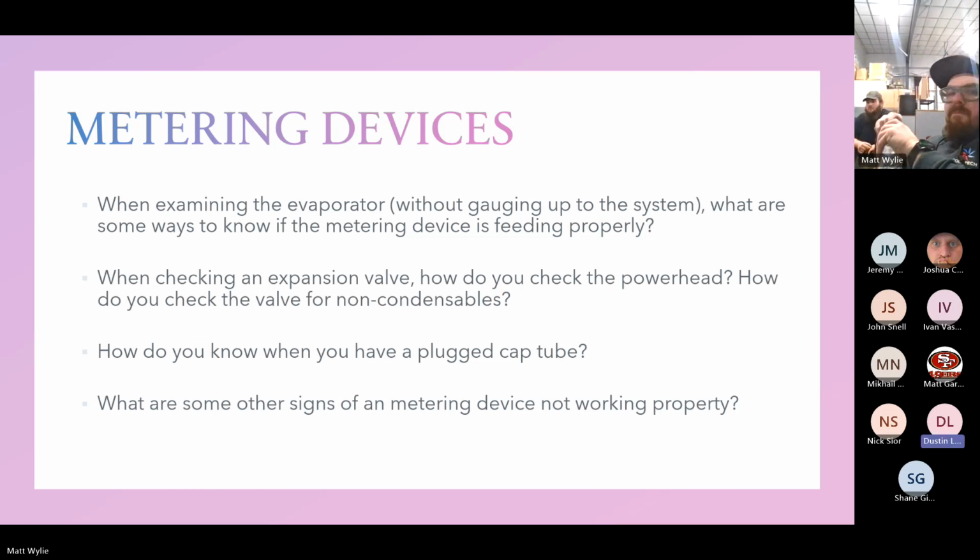If you have your hand valve closed and pumped it down, at that point you might as well pull and check the screen while you already have it pumped down. Then, before you adjust your superheat, you're starting with a fresh, clean screen, and your coil's going to be warmer. It's going to need the refrigerant, so you'll see the valve fluctuate like it's supposed to.